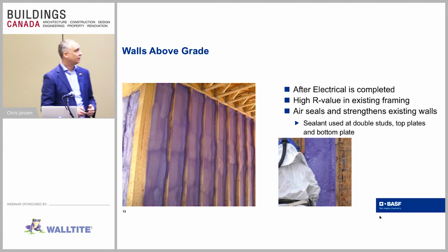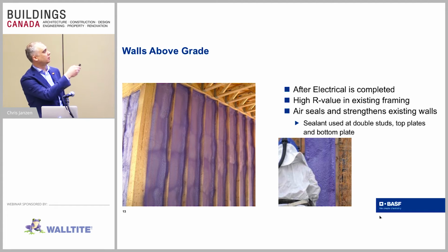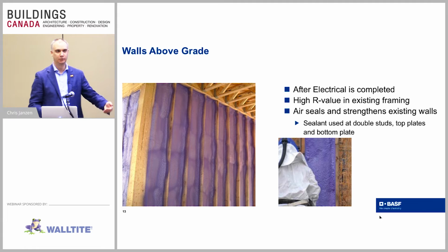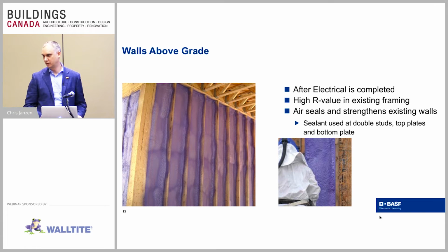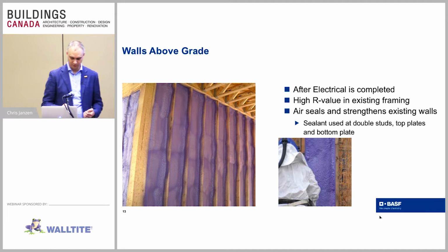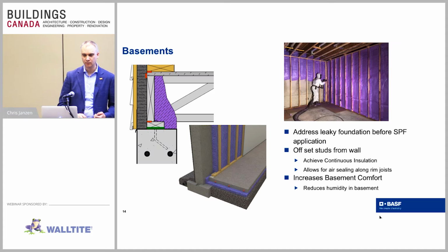And as far as air sealing, that's where you want to make sure that stuff like this, where you have corner studs, top plates, and where the bottom plate meets the floor, that's where you want to run a bead of caulking, either an elastomeric polyurethane type of caulking or an acoustical type of caulking, to make sure that all these wood-to-wood joints are sealed up, and the spray foam on the inside is going to seal the majority of the building and the wall for air leakage.